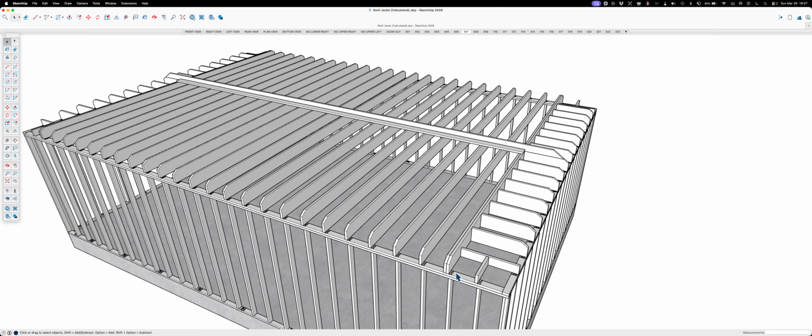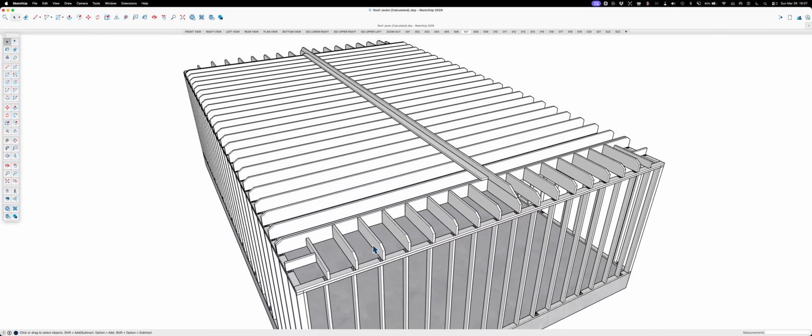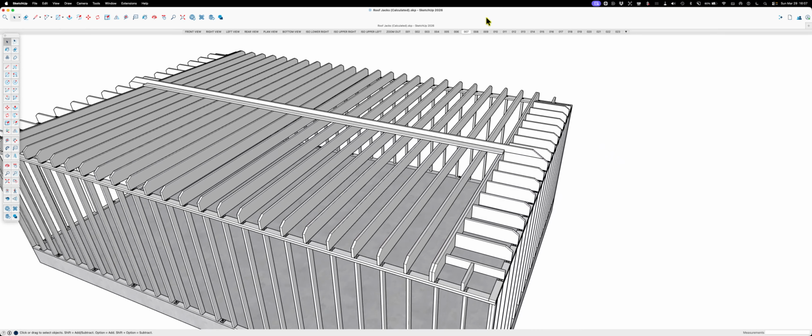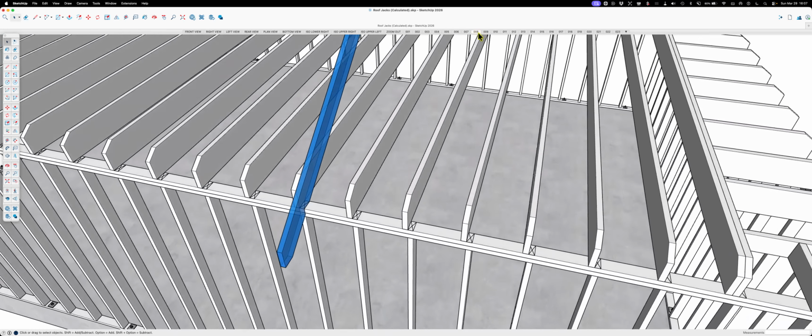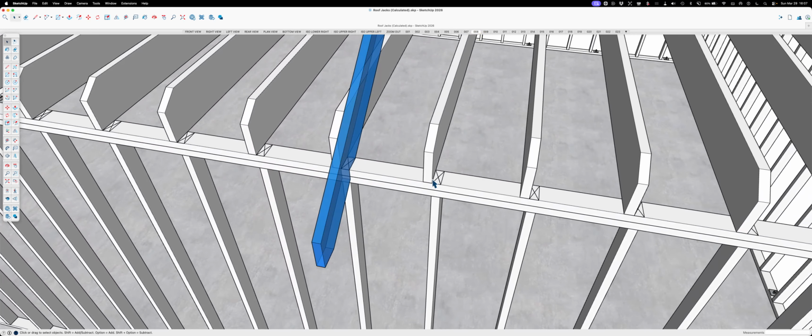Anyway, so the reason why these in the corner are lower is because there's going to be some hips come down. This is going to be a hip roof all the way around, 8 and 12. And that's why they're a little different. You need more space down here. So these are the layouts. And when I said stack frame, I always stack frame to where the rafters go in line with the studs.